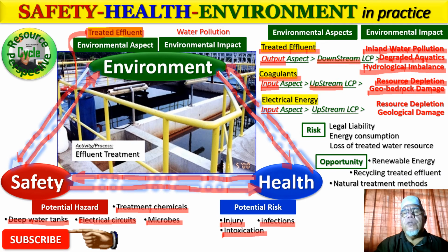So in an environmental management system, we are supposed to have a very good operational procedure on how to use coagulants in an industrial effluent treatment system. The word how directly means operational control, SOP, for the use of coagulant in the industrial effluent treatment system. So as IETS operators or wastewater treatment plant operators, technicians, engineers, we have got to use these environmental aspects of coagulants in a manner stipulated in the IETS manual, in order not to introduce excess coagulant or insufficient coagulant.